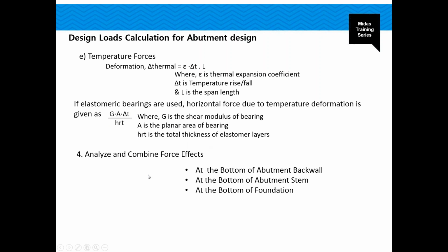So finally, after getting all the force effects from the superstructure and the foundation, we combine all of them. So there are three critical load locations where the force effects need to be combined appropriately and analyzed for an abutment design.